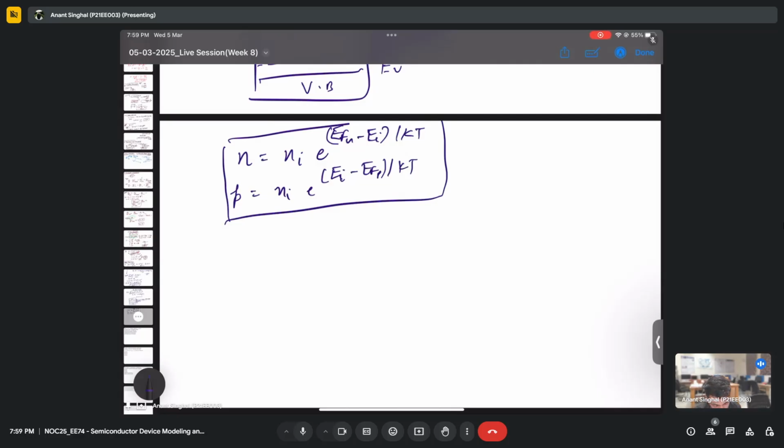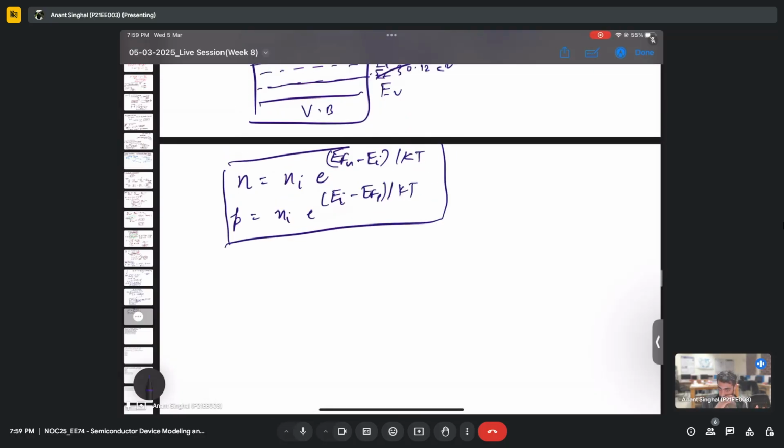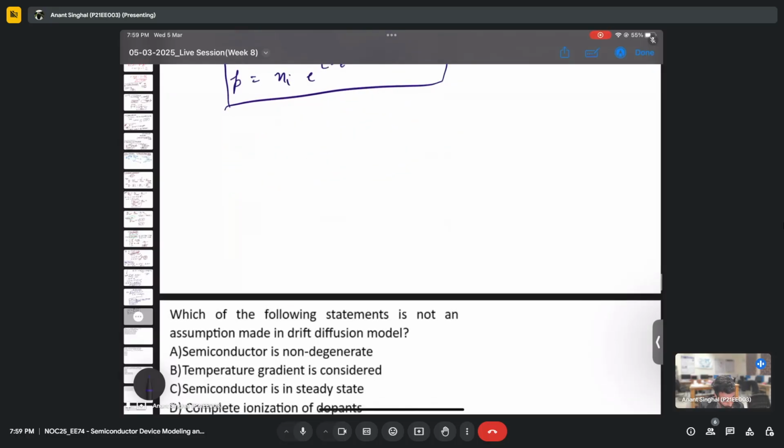This condition occurs only when we inject carriers, that is, a non-equilibrium condition. It can also happen if we apply a voltage. You might have seen the band diagrams of a PN junction at applied voltage. There were two different Fermi levels. Remember? So whenever the device is not at equilibrium, there will be multiple Fermi levels. That is what the quasi Fermi level is.